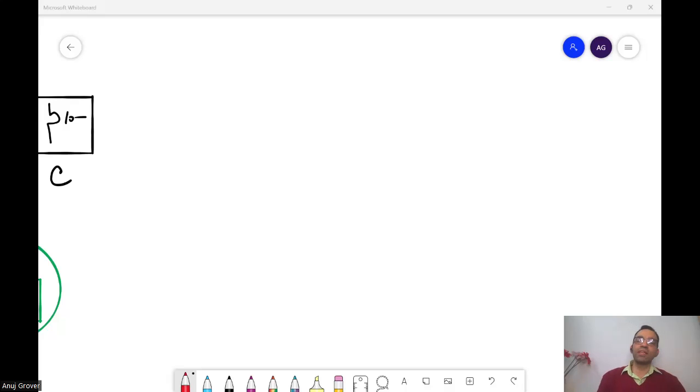Okay, so we are saying that the capacitively coupled sense amplifier and the third one that we talked about is called the alpha type sense amplifier. Okay, in the capacitively coupled sense amplifier and the alpha type sense amplifier, we could actually have the sense amplifier operating at a different voltage than the memory array. So we could really reduce the sense amplifier supply and overall have significant dynamic power reductions.